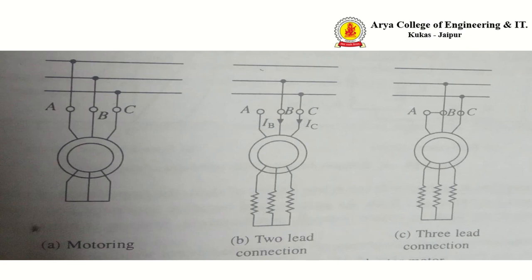During braking, if the rotor speed becomes greater than the synchronous speed, then the relative speed between the rotor conductor and the air gap rotor field reverses. Then the rotor induced EMF and rotor current reverse, and stator current conducts which balances the rotor ampere turns. Consequently, the phase angle becomes greater than 90 degrees. The power flow reverses because the phase angle is greater than 90, and when power flow reverses, the motor rotation also reverses. This is the regenerative braking process.